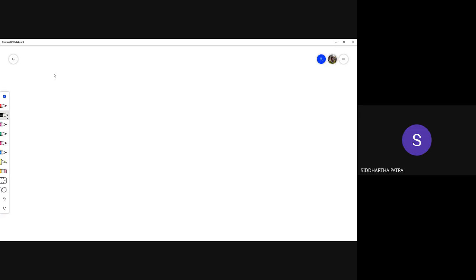Now, since we are working in 2D, this is how our strain in Voigt notation looks. Again, we are using small strain notation, so it is composed of only three components: epsilon xx, epsilon yy, and gamma xy. What are their expressions actually?